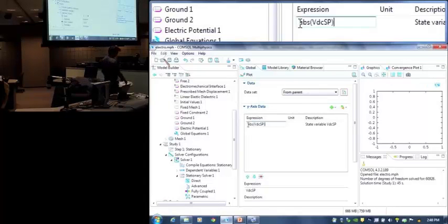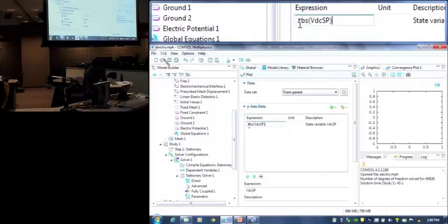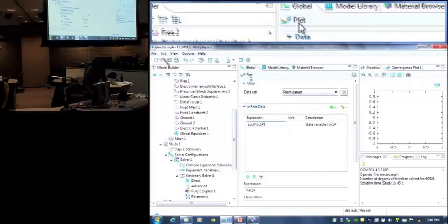It's more mathematical than anything to do with physical sense here. So when you calculate electromagnetic forces, it depends on the gradient of V squared. So that means the solution for that is either plus or minus mathematically. So when you back calculate the potential, it can return you negative magnitudes of potential as well. So we're not worried about the negative magnitudes of the potential, but it will still have the same physical effect. It's just the magnitude will be negative or positive, doesn't matter as far as mathematics is concerned here. So I'll take the absolute value here and click the plot sign.